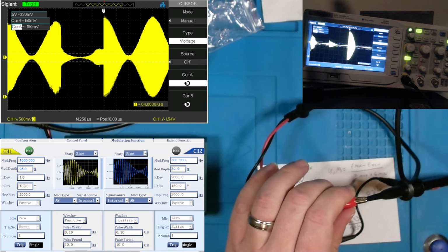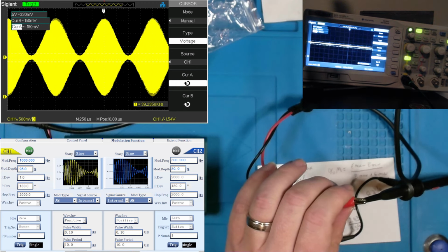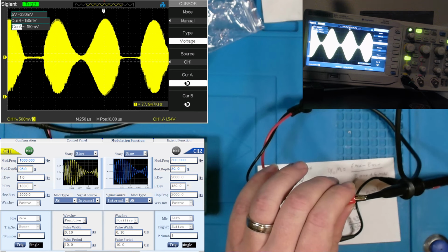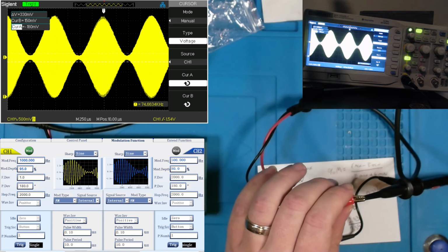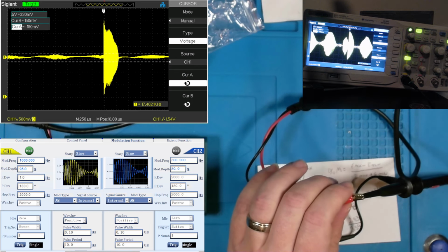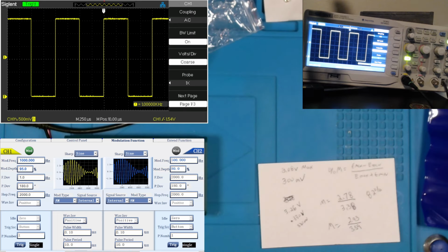Traditionally, when you have bad modulation, your waveform is going to be very asymmetrical. But I think that would be a decent example. But again, you can have a modulation meter still telling you you're at 80 or 90 or whatever, but physically seeing that waveform is very important. So we've done AC now and DC. We've looked at a modulated waveform, AM modulated as an example. What are some other things that an oscilloscope can do for you?